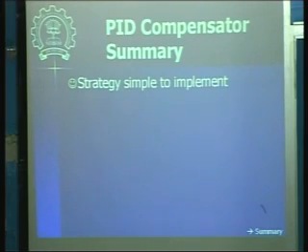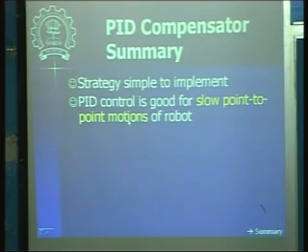Now let us summarize our PID control compensator. Again, this is a strategy which is very simple to implement. You don't have to do any nonlinear computations. We'll see next why in some other strategies we have to do these nonlinear computations, but in PID control we don't. It is very good for slow point-to-point motions of the robot, mainly because it is now taking care of the steady state error.